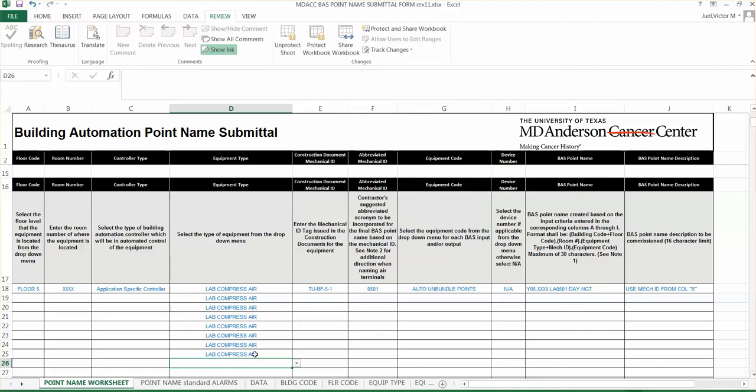Let me cancel that. So the other thing I learned too, this one will work the same. You want, let's say, a heat exchanger. Now, if you select the box, type in the letter H, and then hit the menu, it doesn't work. To get to the H section quickly, type in the H, click here, and go back up to here, click, and then it'll go to the H. I don't know why it does it, but it gets you to the letter category that you want without having to scroll down.